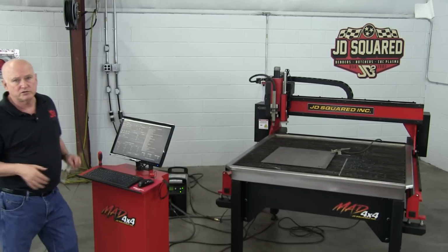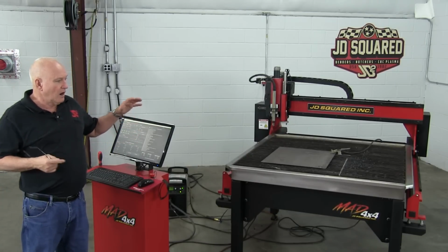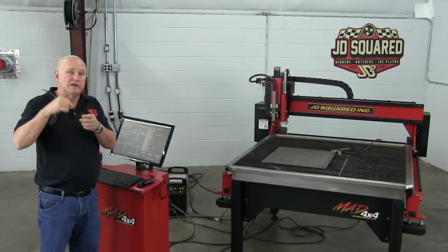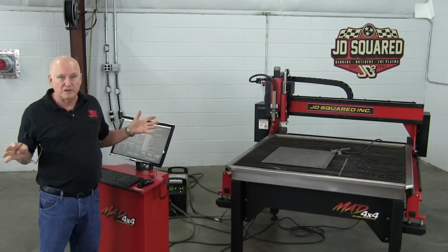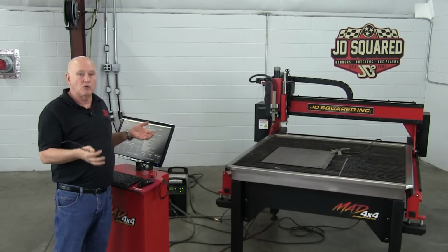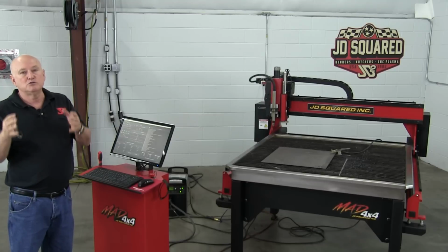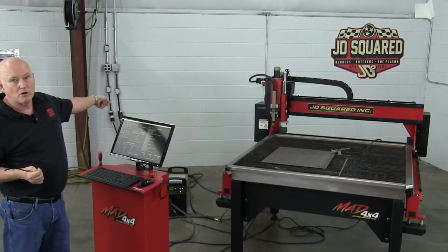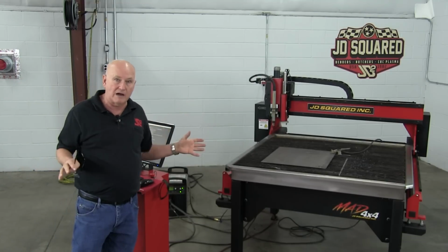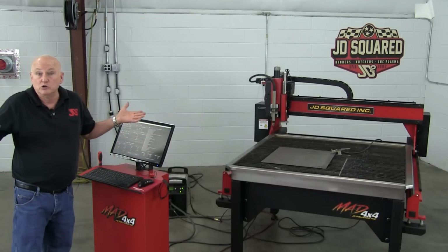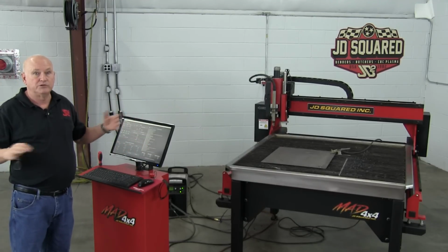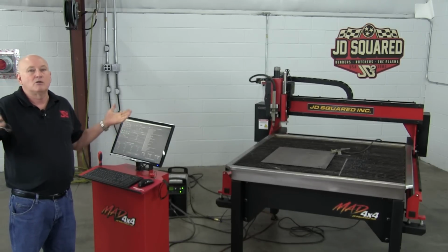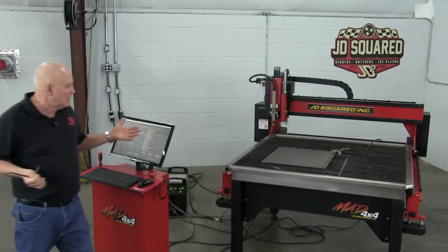This is hugely valuable. And the reason is our machine has one purpose in the world, and it's put that torch where it's supposed to be at the right speed, the right height, the whole bit, and do what you tell it to do, what your voltages are, what the kerf is, right? If the cut goes bad and the machine's running fine, you can almost guarantee it's either we got a wrong amp setting there, we got wrong consumables, we got worn out consumables. You could be trying to cut aluminum, for instance, with air. No, don't do that. You're going to have to use nitrogen or something like that. But there's a million things that, like my daughter once said, she goes, there's 1,000 ways to die cutting plasma. Those are some of them.